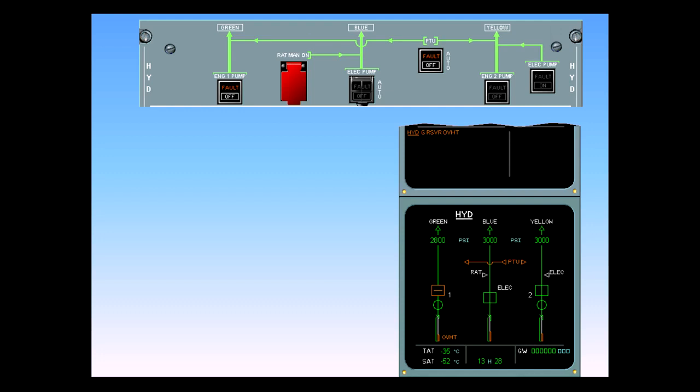The following indications show that the green engine 1 pump has been switched off. Push-button switch off light. ECAM hydraulic page green engine 1 pump has changed from green inline to amber crossline. Notice the pressure indication is dropping. Again, notice that the blue action item has disappeared.